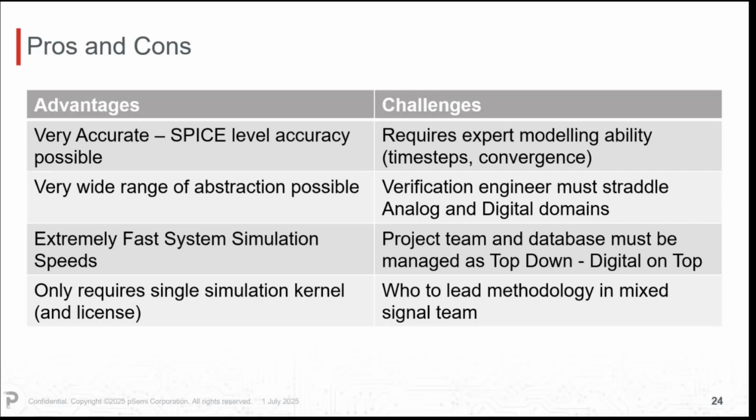There's a very wide range of abstraction possible. Your verification engineering really needs to straddle both the analog and digital domains to get the best of this. Huge system simulation speed. So you really want to be doing a top-down type approach here. And it only requires a single simulation kernel, which is obviously a potential licensing benefit. That's not the main motivation. The main motivation was the performance rather than anything else.